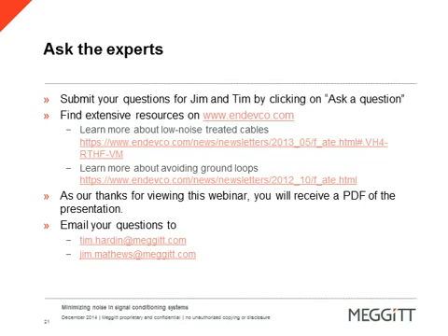Anytime you float the accelerometer, be it through an isolator or an accelerometer that is already isolated because it's designed that way, then, of course, you need to ground the amplifier. Otherwise, you will have improper grounding techniques and you will have noise in your signal. So that is the correct way to do it.